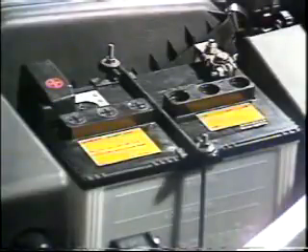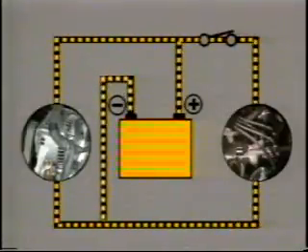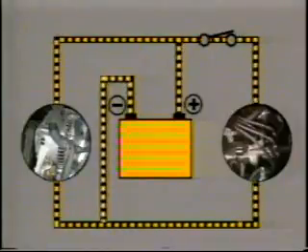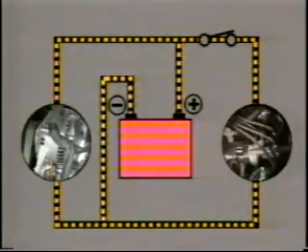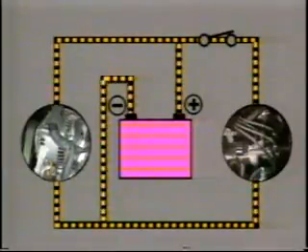Another typical fault is overcharging of the battery. If the battery is overcharged, a lot of bubbles will be seen in the electrolyte, and the electrolyte will decrease considerably, and the light bulbs and fuses will not last long. This is probably caused by overvoltage from the alternator. This in turn is due to a malfunctioning regulator, which allows too much current to flow to the rotor coil. You can also check for this by carrying out a no-load test.